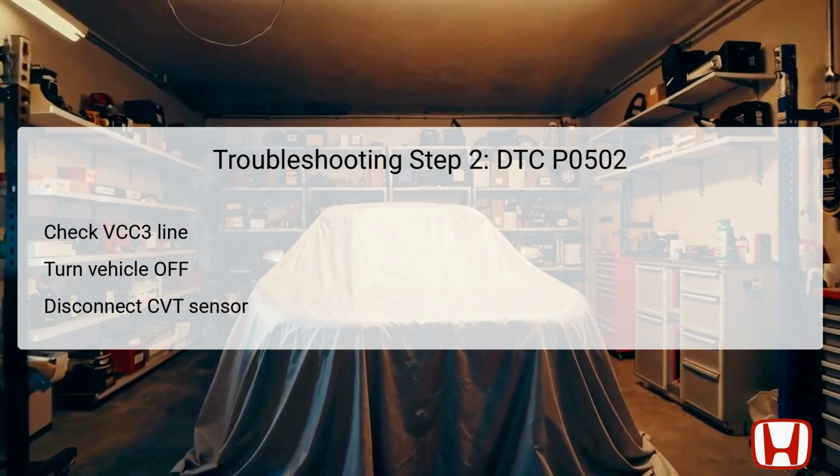In this state, the technician measures the voltage between two specified test points on the connector. Confirming the presence of approximately 5 volts is crucial, as it indicates a functioning power supply to the sensor. If voltage is detected, it directs troubleshooting toward the next steps.